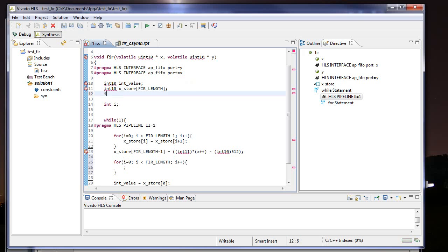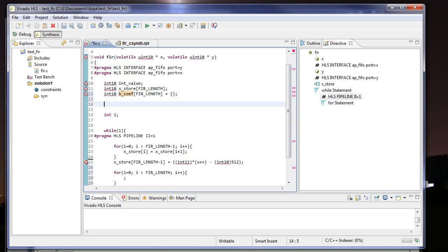So I'm going to choose first the filter coefficients, bcoef, and they're also going to be 10-bit numbers, so you should really validate what the effect of doing this is. And we're just going to preload them. For now, I won't worry about it. So we have a 10 by 10. Obviously, this intermediate value of the multiplication is going to have to be 20 bits.